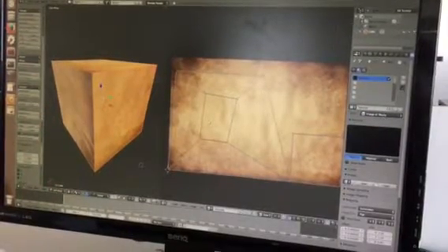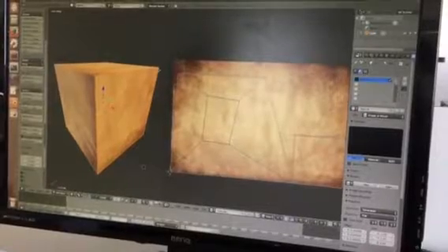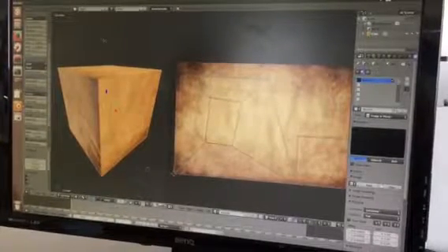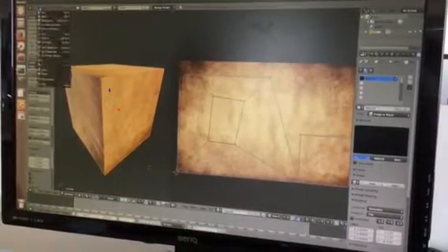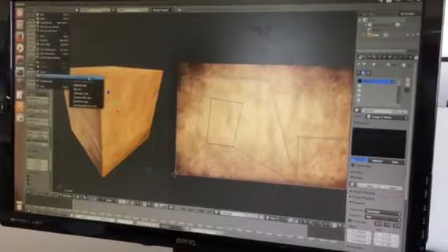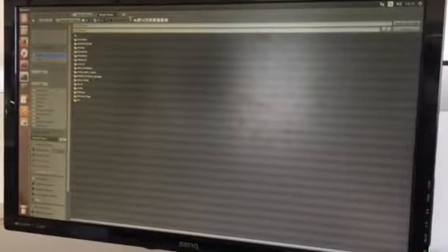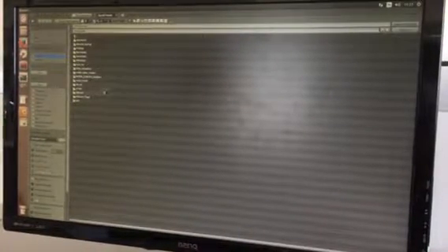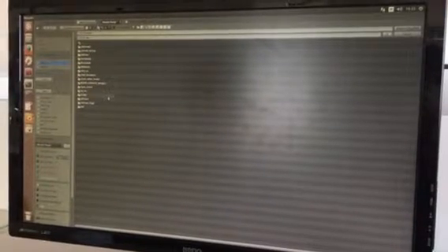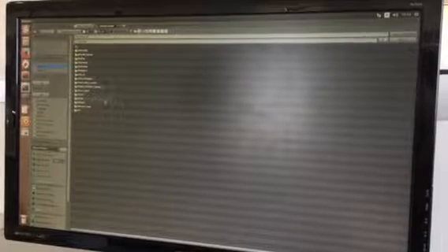Yes. So after you have done that, and you're basically done, now you want to export your model into a collada format. So you click File, Export, and then collada. Again, it is really important that the version of Blender is the correct one, 2.69. Otherwise, newer versions don't support collada export. Really? This is crazy.